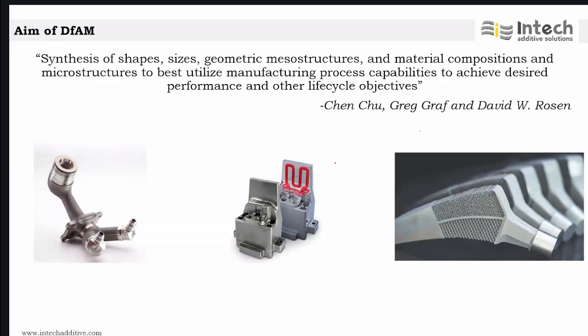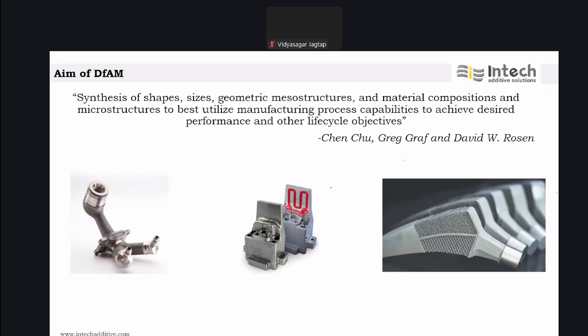And also, it's about desired performance and life cycle objectives. What does this part need to do? What should be its strength, thermal conductivity, biocompatibility, cost or weight? So, DFM actually synthesizes all of this into one optimized design. That is the biggest potential of the additive manufacturing process.